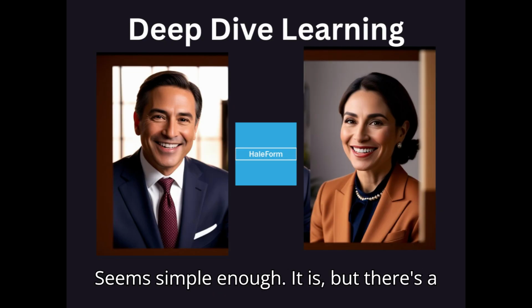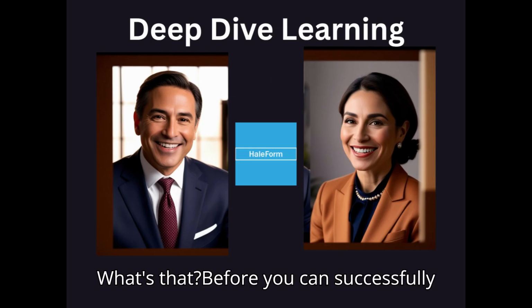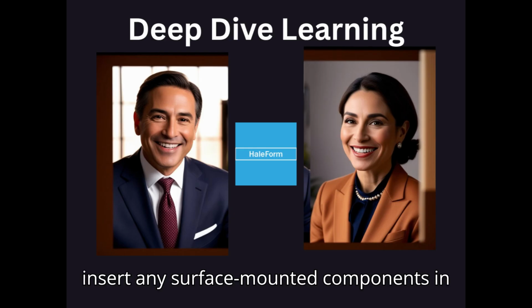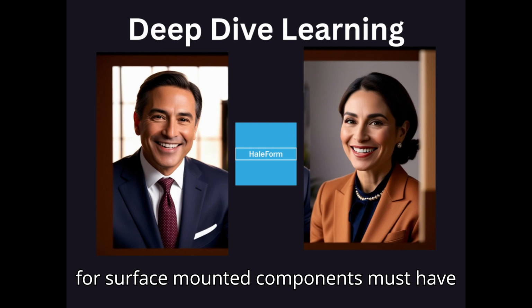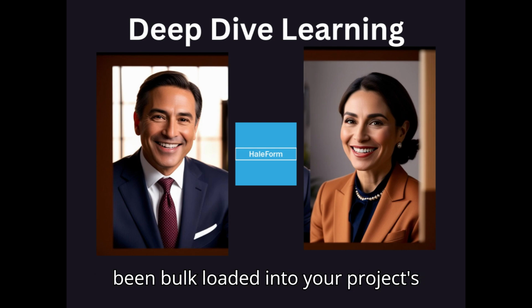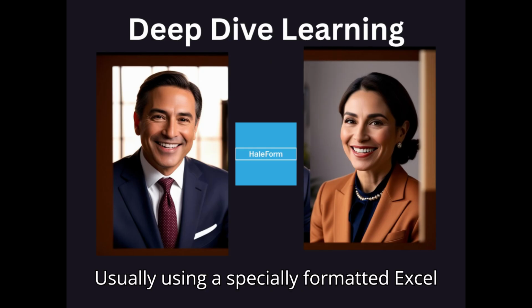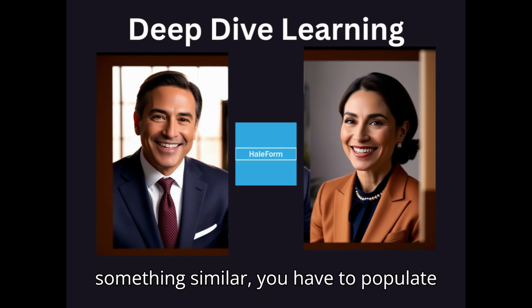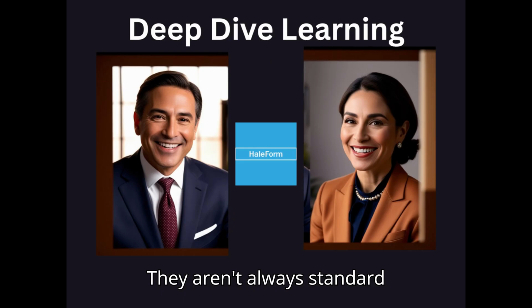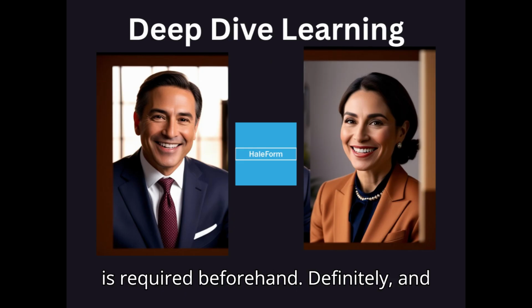Seems simple enough. It is, but there's a really important prerequisite here. What's that? Before you can successfully insert any surface-mounted components in your project, the necessary sample data for surface-mounted components must have been bulk loaded into your project's reference data. Bulk loaded. How? Usually using a specially formatted Excel workbook, often called PCF.XLs or something similar, you have to populate the catalog with these definitions first. They aren't always standard out of the box. Okay. So some setup is required beforehand.